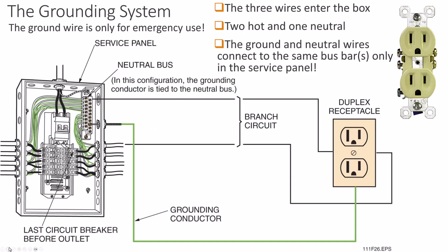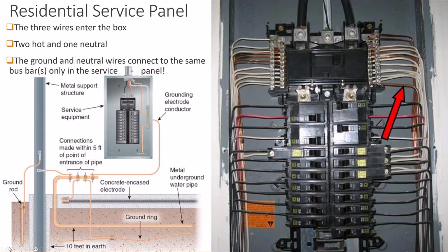And then ultimately to your electrical outlet, to your electrical light socket, those kind of things where you've always got to have a hot wire and a neutral wire. And if you've got, let me back up to the other picture, if you've got a double wide breaker, well, then you're getting electricity from both of those black wires to give you 240 volts for central air conditioning unit outside. If you got an electric dryer to hook up, or an electric cooktop or oven, you're going to have 240 volts for those kinds of things. An electric hot water heater, maybe.